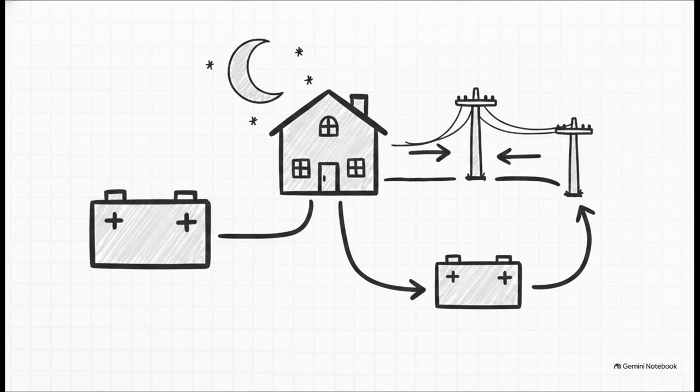So the crucial takeaway here is that while panels can handle the rain, they for sure do not produce power in the dark. Without photons, the whole physics process we just covered literally stops. But there are some pretty robust solutions to make sure your house stays powered up after sunset. You can store your excess daytime energy in lithium-ion batteries. You can use net metering, which basically lets you export your daytime extra to the grid in exchange for credits to use at night. Or you can go with a hybrid system that smartly switches between the two.